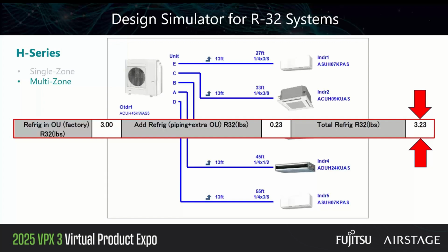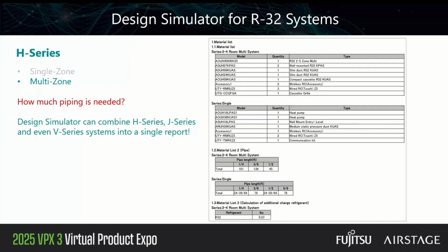So as I mentioned, a huge majority of the time you will not need to worry about LDS accessories. And even when you do, again, a gentle reminder that our ducted units, H series and J series, have a factory installed leak detector. So we'll talk about that more.